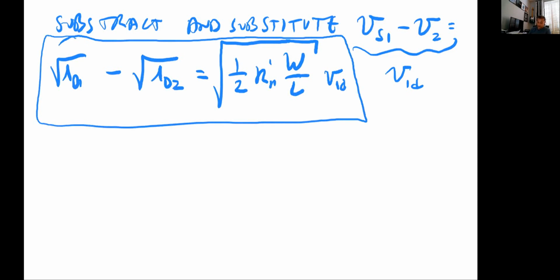But I can also recognize that, just to simplify things, the sum at any time of the drain currents is going to be equal to my bias current.